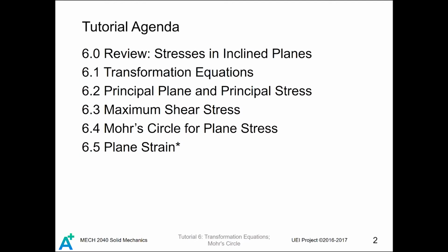Another important thing in this tutorial is to combine all our transformation equations into a Mohr circle. It can give you a very direct impression of the relationship between the direct stress and shear stress for an element at different orientations. We also talk about plane strain.